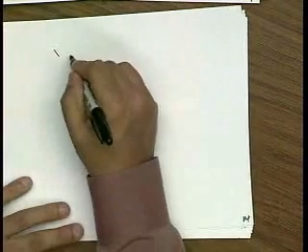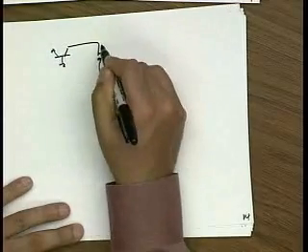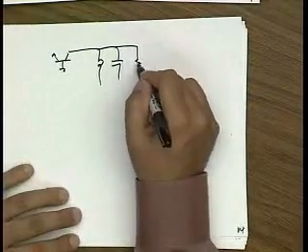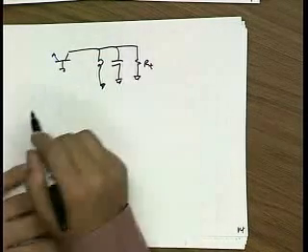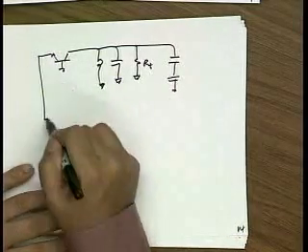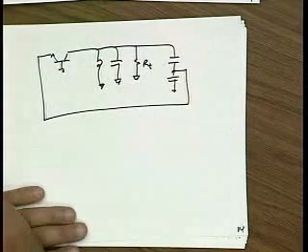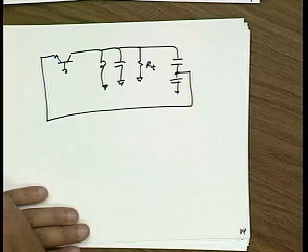Okay, so what do the design equations look like for the common base oscillator? Again, I have my tank. I have a resistance here that models the total tank resistance. And then I'm going to have a feedback network as follows. Now, does anyone notice a disadvantage to this oscillator compared to the common emitter oscillator?